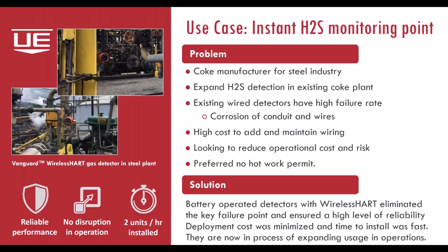So they needed to find a solution that they could put in and not have to worry about the detector as much, and more rely on the information that it was providing, that, hey, there's a high level of H2S in a particular area of the plant that needs to be addressed. They came across us when they needed to put one in quickly. They felt that since it's wireless, they'd do it temporarily. We put one in, and they were very happy with it, and they are now looking to replace all of their wired detectors with wireless, because of the simple fact that they don't have to maintain the wires anymore. They don't have to worry about conduit if something got damaged or leaked into, and the corrosion occurring to the wires themselves.